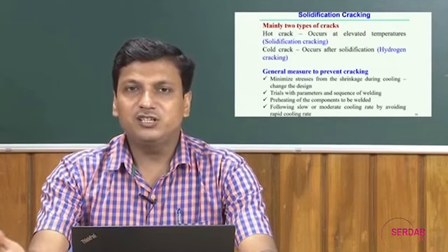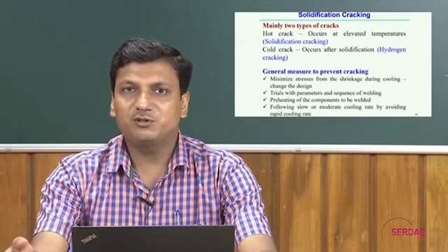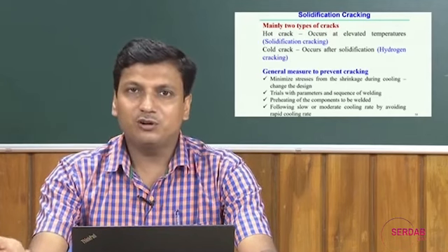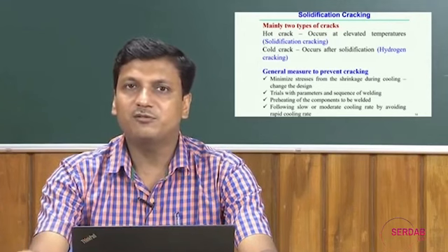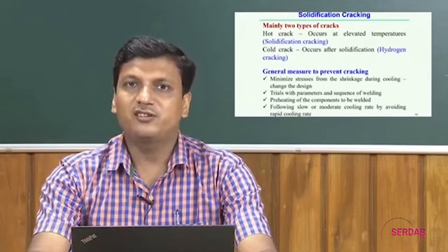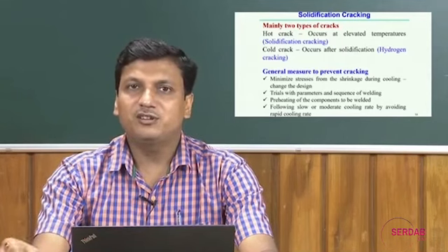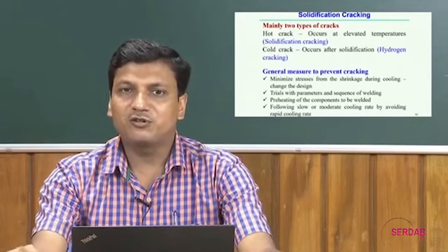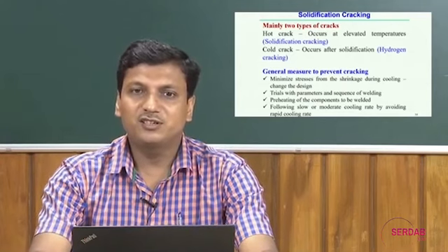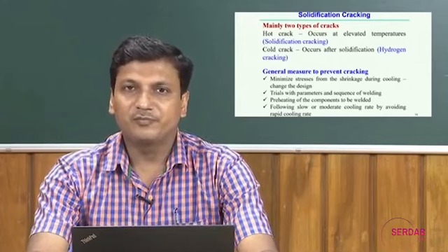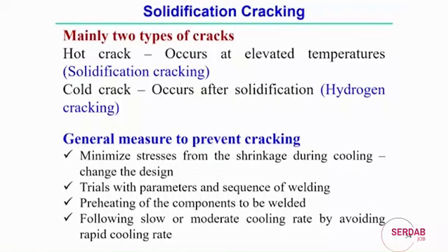So, change in design in the sense that if it is possible to control the rate of cooling, maybe with the aid of some other external heat or cooling process, mainly the cooling rate can be controlled to minimize the stress during the shrinkage process in solidification.